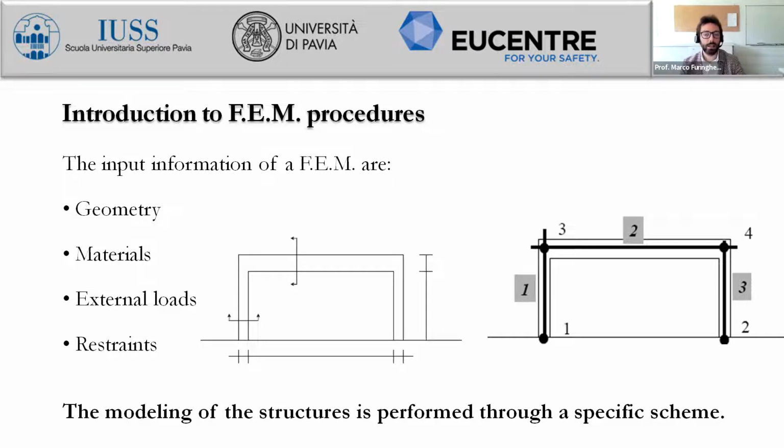section we are designing, and we have to remember that these lines have actually a lot of information within all the points of the line, which are actually the cross section and all the material properties and all the sectional properties. But we are just considering a line. And then we have to keep in mind one important concept about finite element modeling, which is actually the following. We are going also to use SAP2000, and we will draw actually our geometry and our structure.